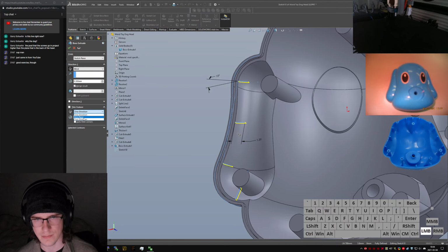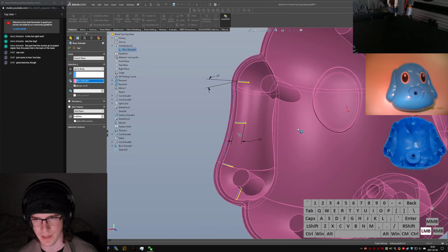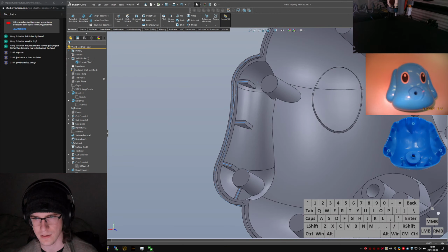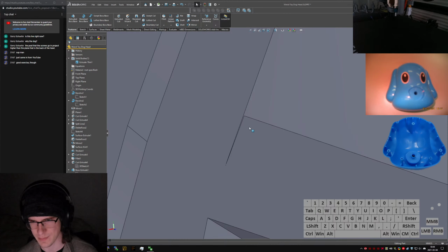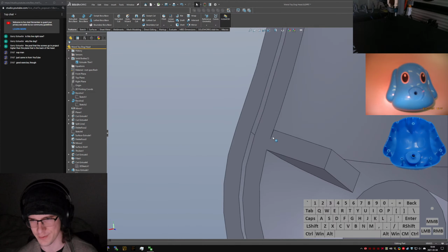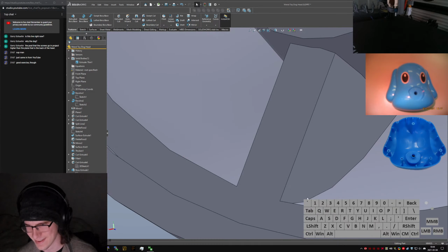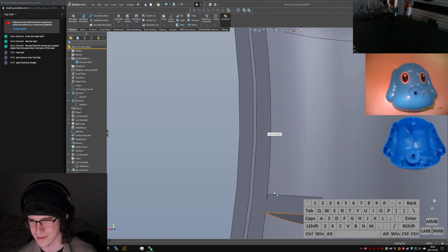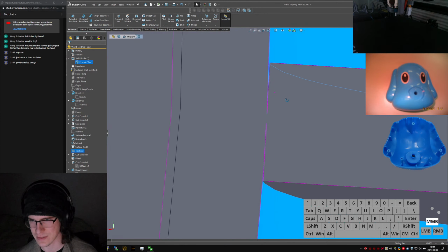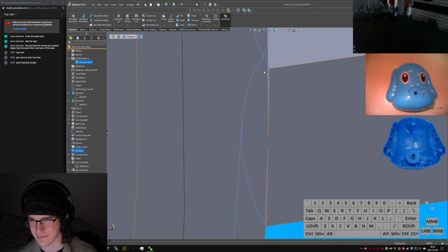Then feature midplane 0.4, not blind, but up to body. Yeah, that does work. Except it breaks a little bit. Super cool. Breaks anywhere the curvature changes. I'm surprised it's not complaining about zero thickness geometry in there, because that definitely is one of those.